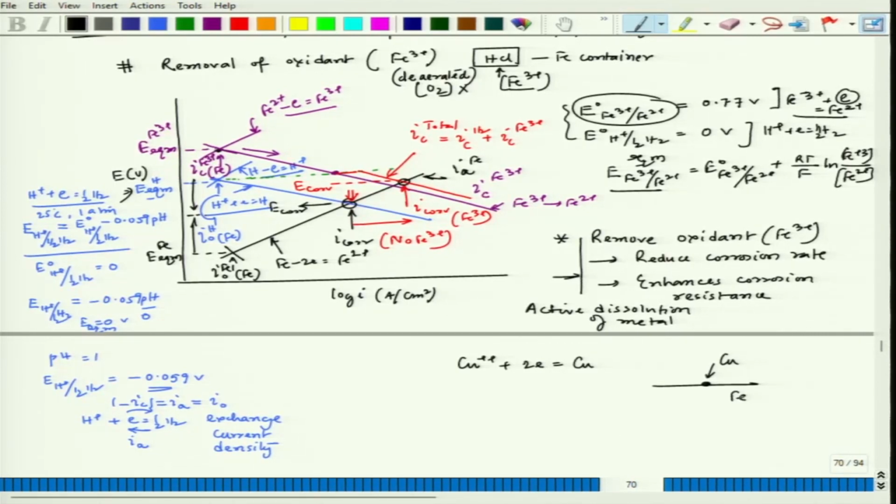So this is iron, let us say, and now what happens, this copper is acting like a cathodic site. So if we have oxygen there, this cathodic reaction would happen on those small cathodic parts, and then close to that copper deposit, the anodic reaction, Fe minus 2e equal to Fe2+, this anodic process would happen, so that the dissolution is localized wherever that copper deposit is happening.